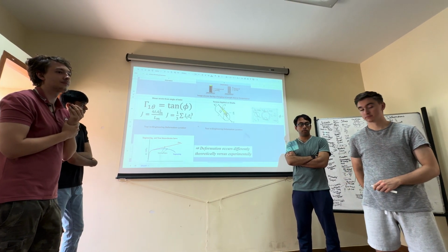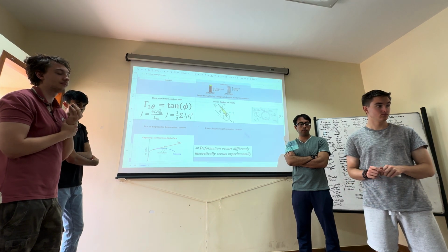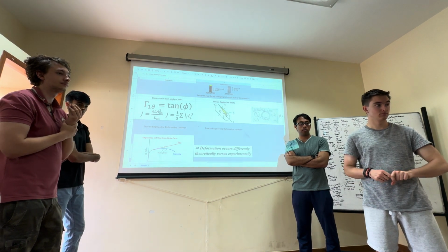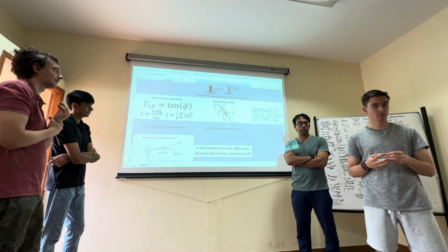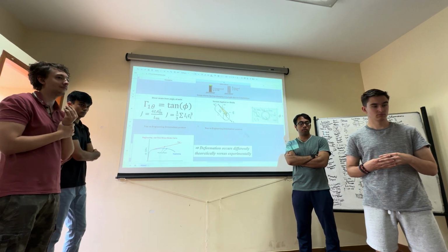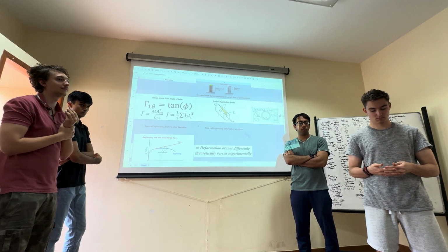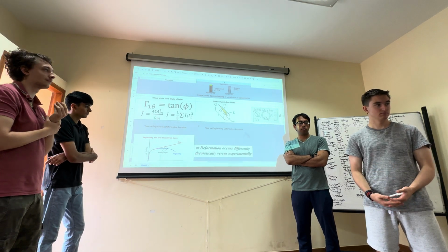Yeah, I'm glad you brought this up because this is one of the important things in structural analysis, especially related to flight vehicle structures, because you'll have both closed and open sections. So there's a huge difference in how the J is defined for either of them, and that makes a difference in terms of the overall torsional behavior of those shafts.